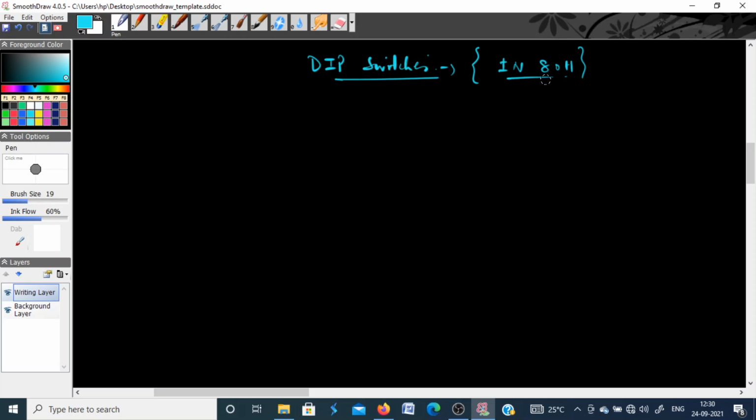Once this instruction is executed, the processor will get the data from the input port identified by the address 80H, and that data should come inside the accumulator of the microprocessor. Now, in place of the latch, you must have a tri-state buffer, and that buffer must be enabled when this unique address is placed on the address bus, and along with that, when the processor asserts the input-output read signal. So in place of a write operation, now you have a read operation.